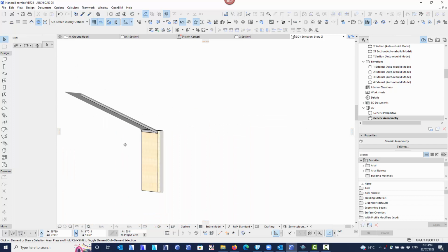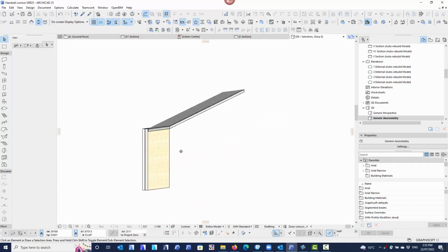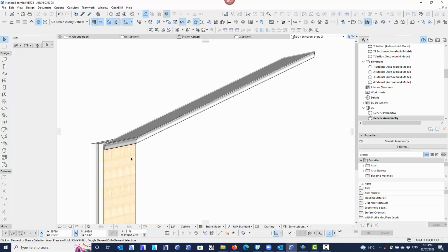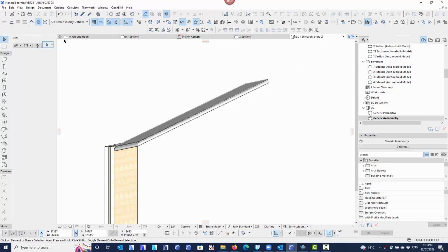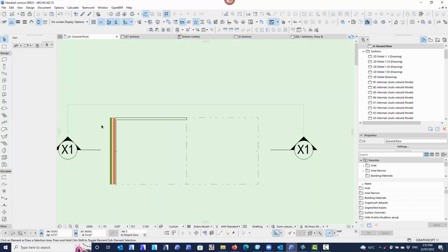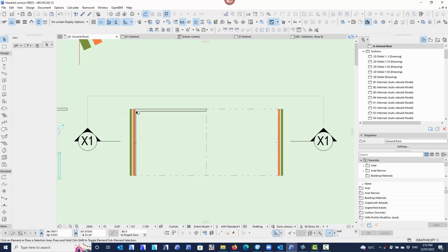With the beams, you'll find it's a little bit easier than with the cornice tool, so you don't have to worry about which end is which and this end is straight and all that sort of stuff. So two beams that touch each other, the corners will mitre. It doesn't matter if the beams are on different angles, different rolls. As soon as the reference lines touch, it will mitre. So that's quite a nice way of doing it as well. It's possible to do that all with beams.